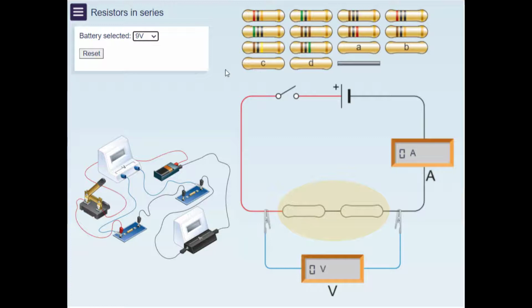To measure the resistance of a single resistor, select the resistor and place it into one of the slots. To complete the circuit so that the current can flow, you will also have to insert a wire into the second slot. Once your components are in place, switch on the circuit. Make sure you record your resistor selection, the voltage and current readings in your laboratory notebook.